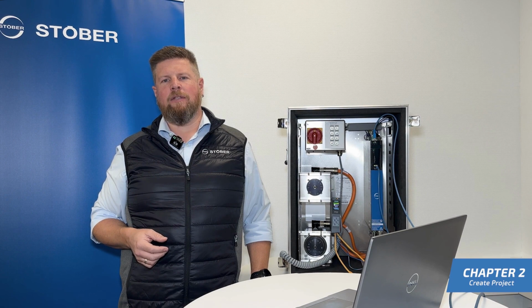What did I just show you? I created a new project, selected the drive controller SC6 A062 with the firmware for Profinet and set the control to PROFIdrive via Profinet. After that, I configured axis A with the motor EC401.